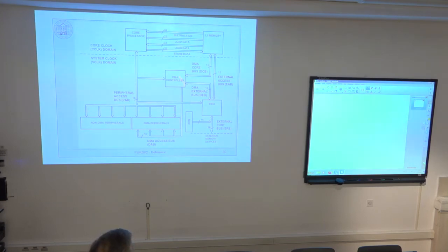So you simply program this DMA controller that immediately once a new value is available on some DMA supported peripheral, this value would be read out from the input register and automatically written into memory to the corresponding location, to the address that is part of this DMA controller.